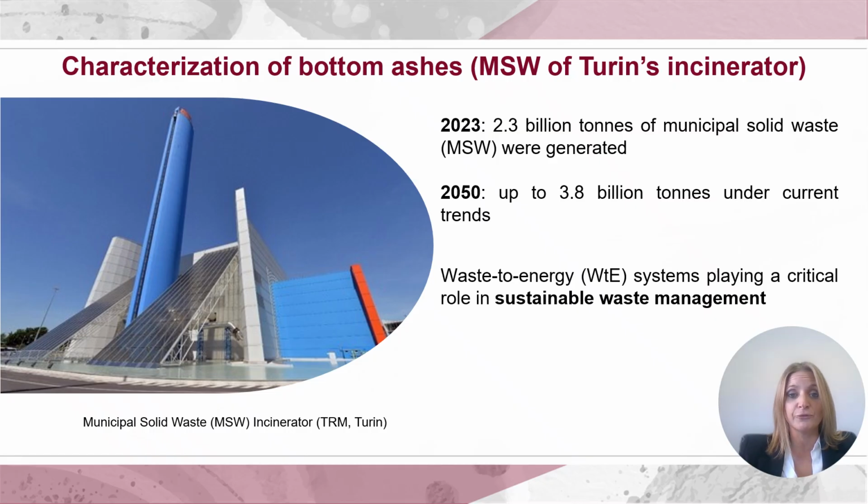Our case study focuses on the bottom ashes produced at the Turin incineration plant, northwestern Italy. This facility, that you can see here in the picture, converts municipal waste into ash at a ratio of roughly 5:1. So the goal of our work is to characterize these residues and develop a low-cost inertization method suitable for their specific composition.